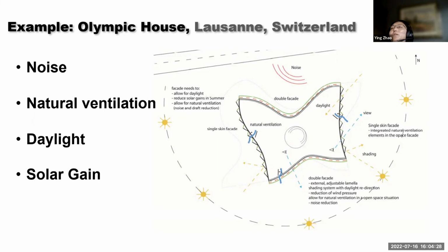So it won't help very much. It will help, but the heat still goes inside, it already goes inside. So consider an external shading device. For the double skin, they put it inside, because there is still an inner skin there, so they can control solar gain inside the double skin.